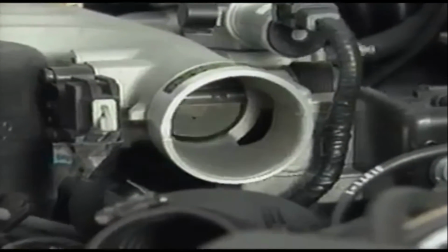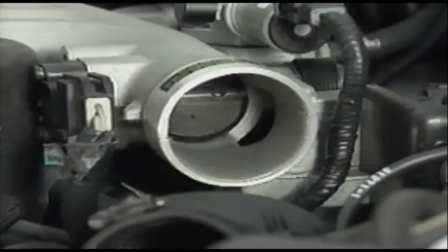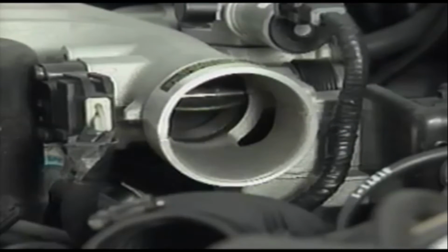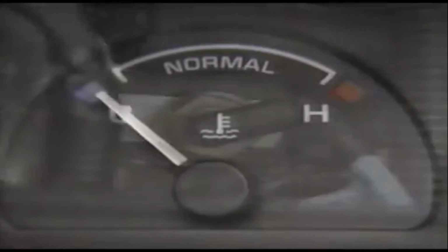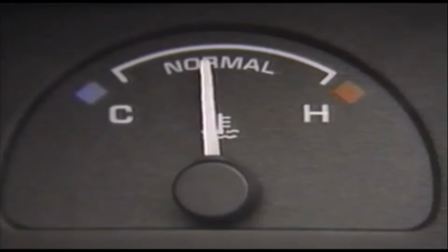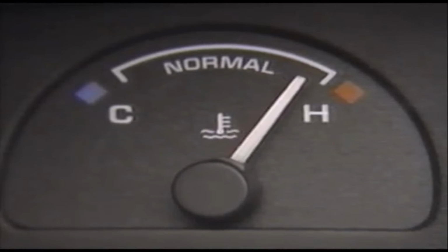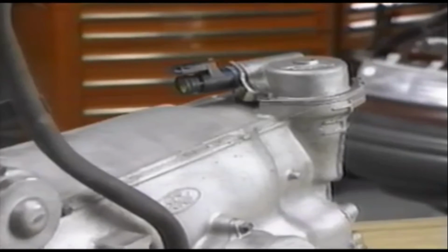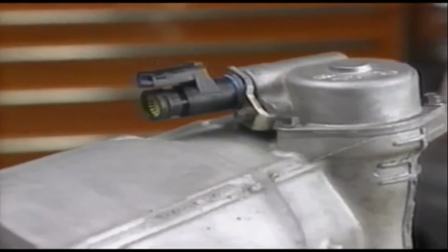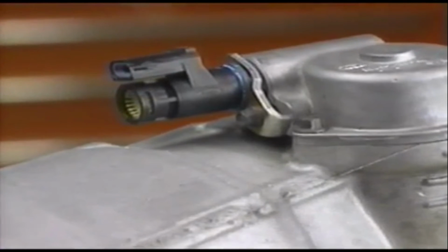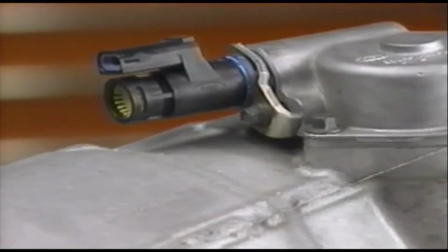Some variable resistors, such as the throttle position sensor, change their resistance value according to the movement of an attached component. Temperature sensors, or thermistors, are used to operate this temperature gauge, for example, since they vary their resistance value based on temperature. The speed sensor is used in place of a speedometer cable and converts magnetic pulses into a voltage that can be used by the electronic speedometer and the EEC4 control unit.